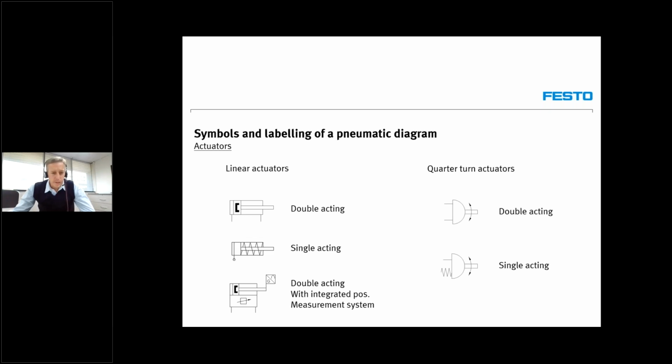I'm just reading Rakesh's comments here. He says we're using common air with the FRL, which is the service unit before the solenoid valve. No separate instrumentation air is used. We are using a refrigerated dryer with the compressor.